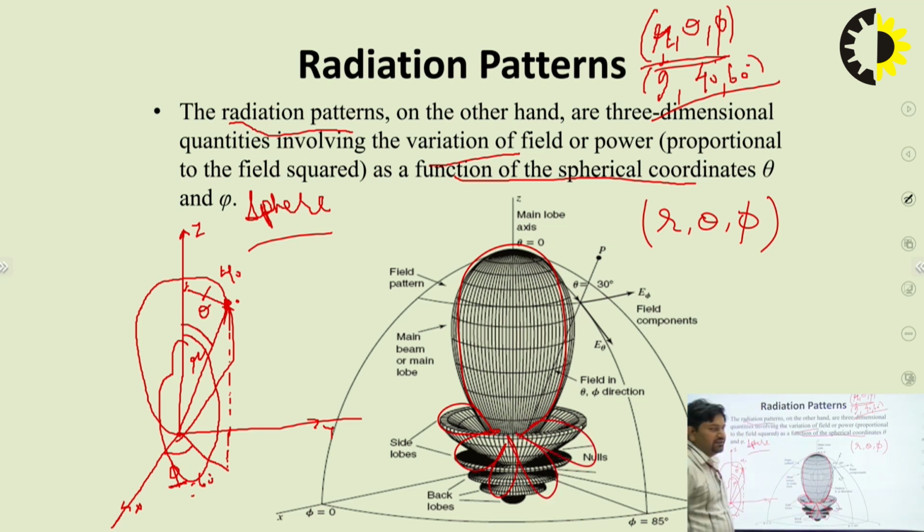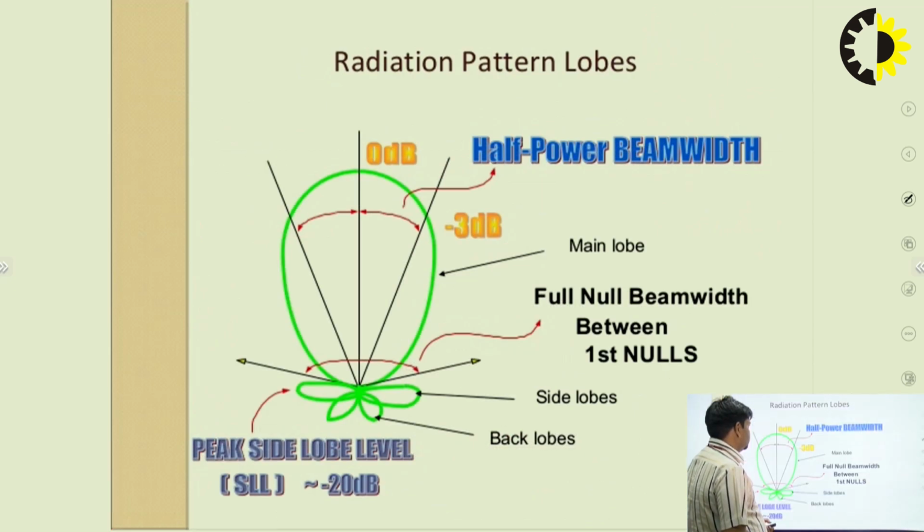The side lobe intensity is very much less than the main lobe intensity. So this radiation pattern is of an antenna which is directive in nature. That means in a particular direction the antenna radiation is high, and in other directions, like the back lobe, the radiation intensity is very poor. So this is the side lobe, an unwanted signal propagated by that antenna in other directions.